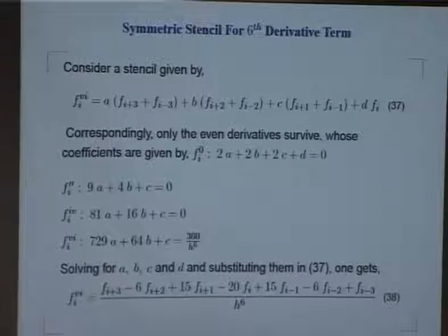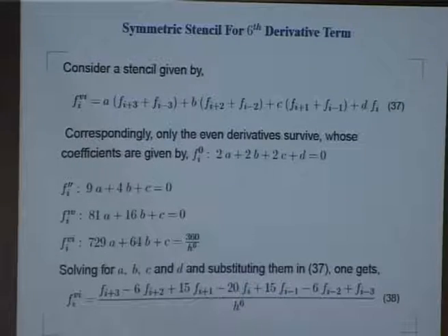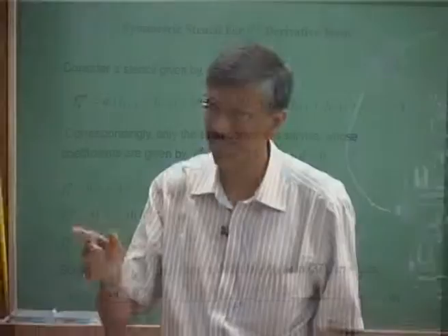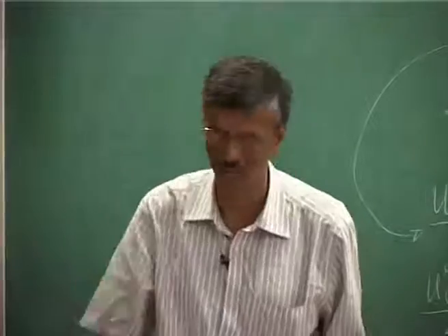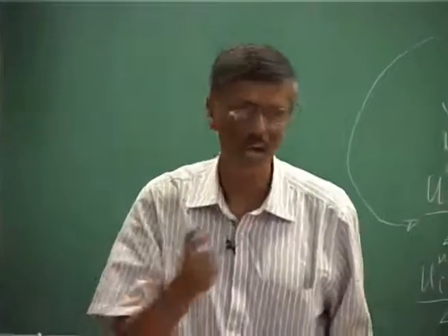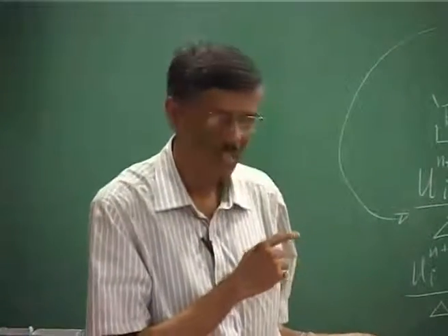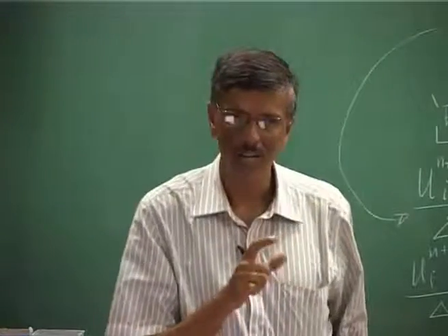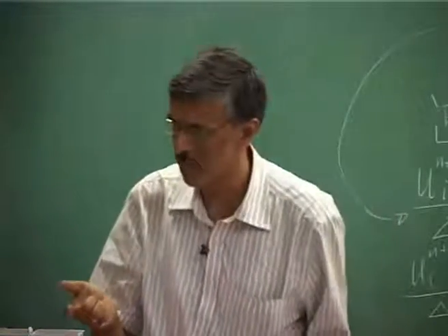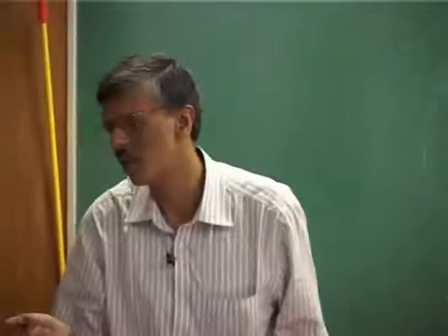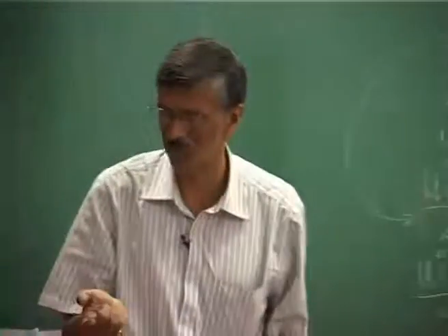Either you can do it by first order upwinding, that is the basic menu. If you do not suggest anything, without your knowledge it will do first order upwinding. And then you understand what it does, that added numerical dissipation actually interferes with the physical dissipation, and the results are of course suspect most of the time.